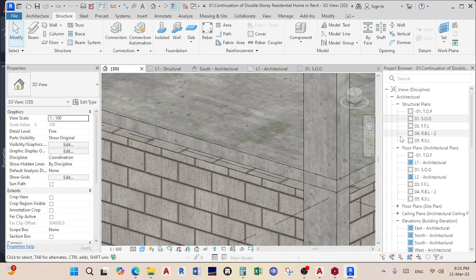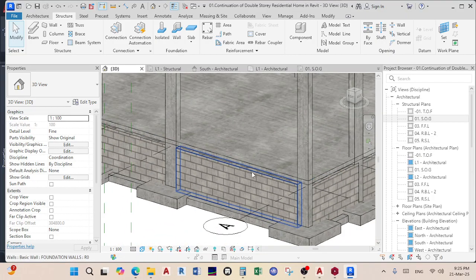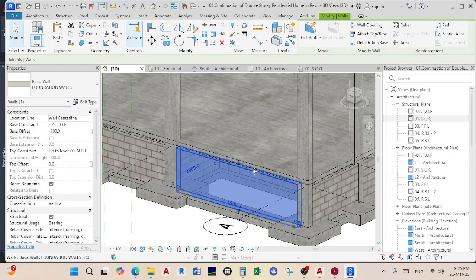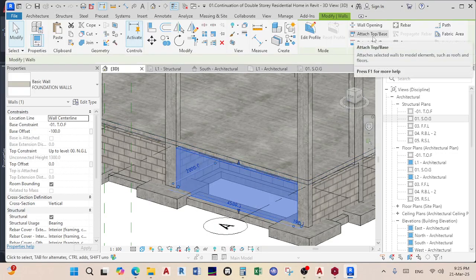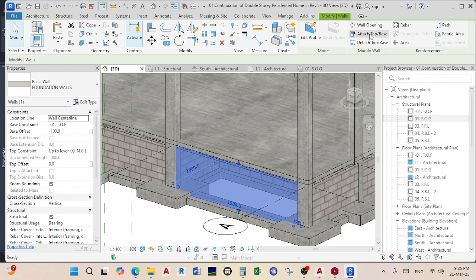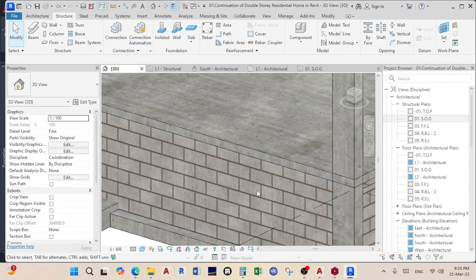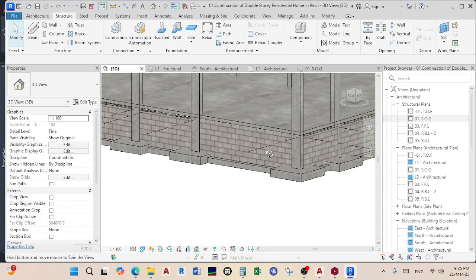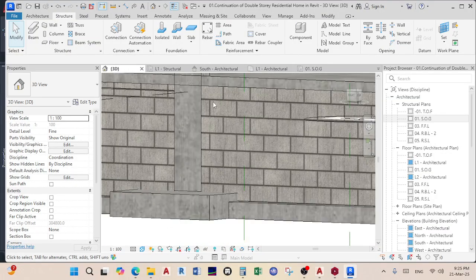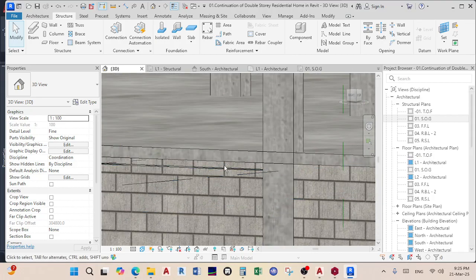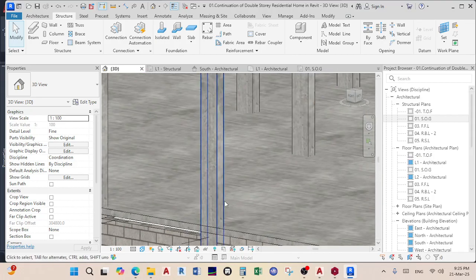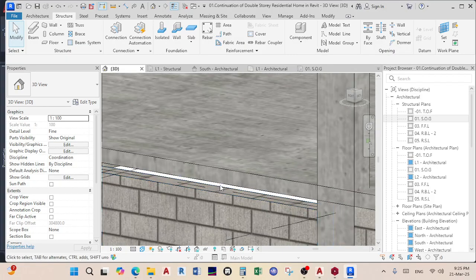Okay, I'll show you both. If you click the wall there, it's got this attach top base. So when you select this and you click what you'd like it to attach to, it attaches to the bottom there. You see? So this side is closed, but then for these other walls, you can see the little space there, right? That one over there.